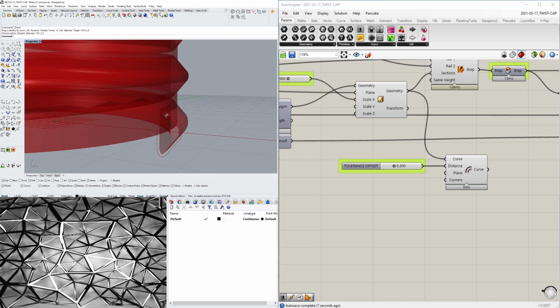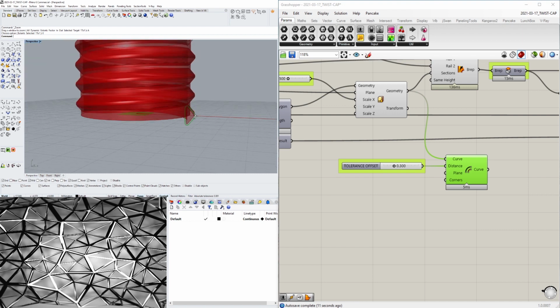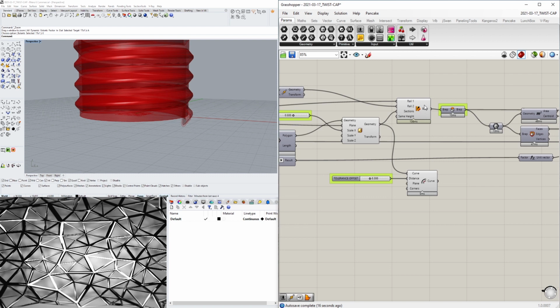Now what I'll do is sweep this one all the way around the same way that I swept this one around, right? So all we have to do is take these two, because we also capped it, so we'll want to do that also. So we'll take this, disable preview, and we'll copy both of these. So there's two ways to do it. Control C and Control V.